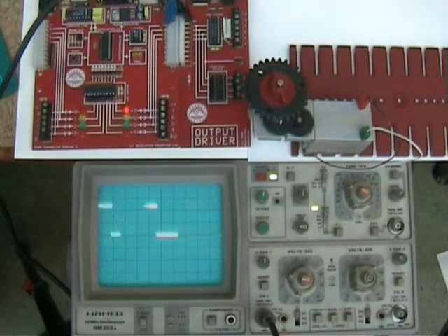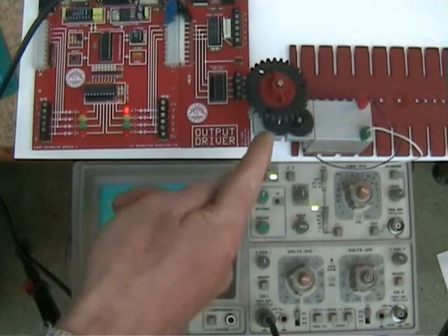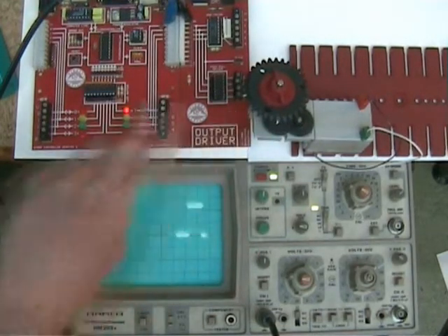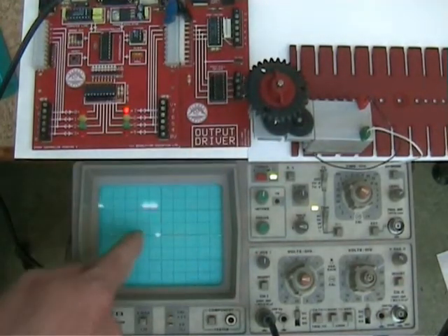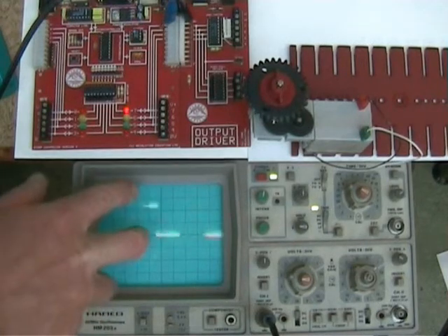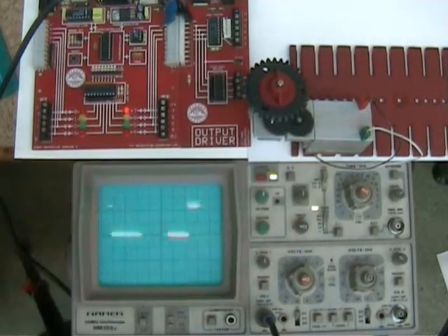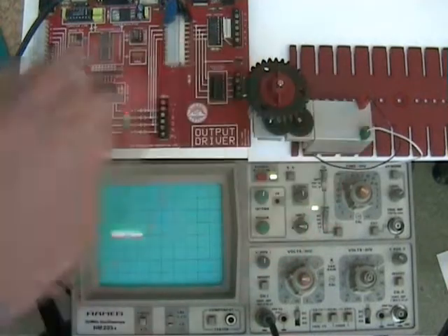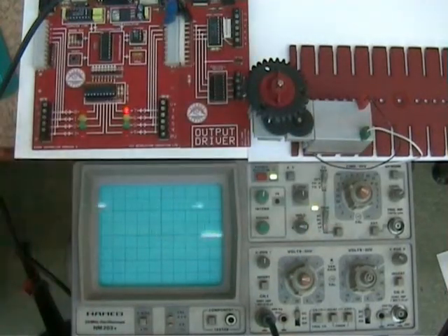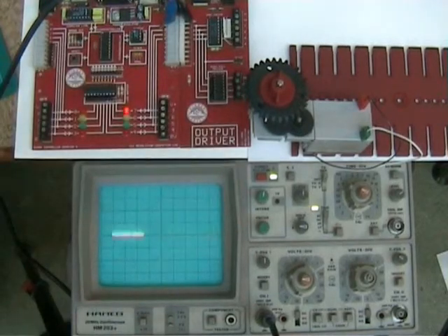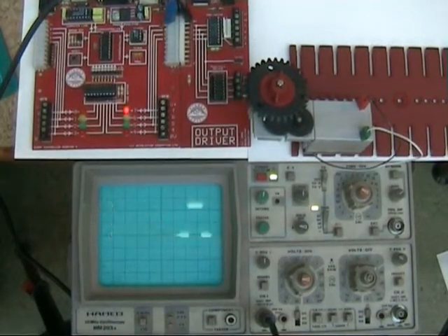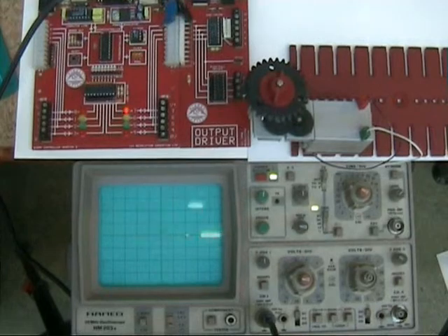The advantage of pulse width modulation is that you can get DC motors to run at very low speeds, and when you're switching on, you're getting the full torque out of the motor. The motor is a 9 volt motor, and the signal coming here is 0 and 9. So you're managing to get it to run with good torque at low speeds. Pulse width modulation, controlling the speed of a DC motor.